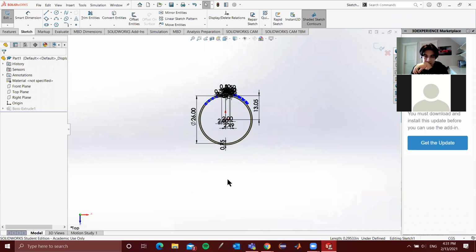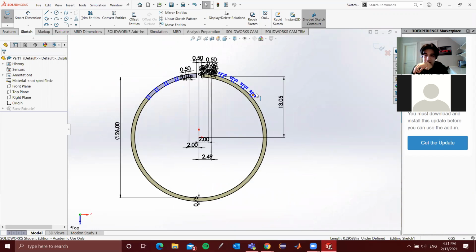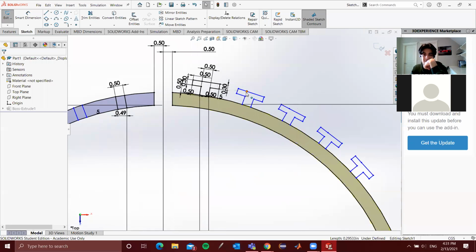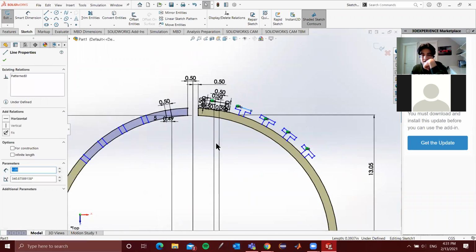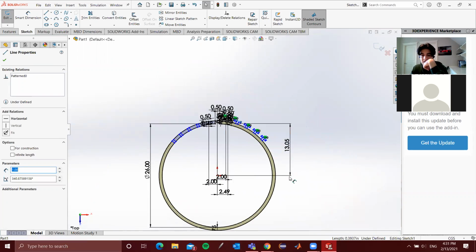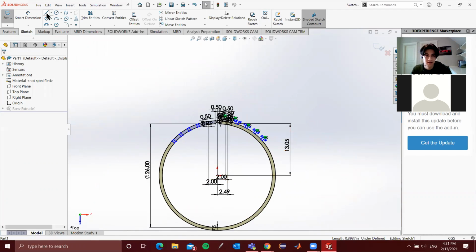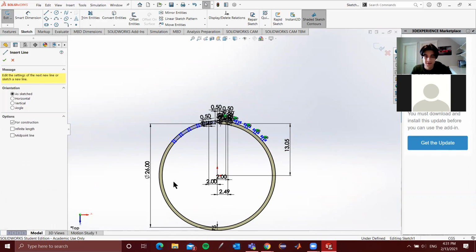So essentially, what we can do is we can reuse these little clips that we had up here, right? And to do that, what I'm going to do is I'm just going to mirror one instance of this one along the x-axis in this case, right? So what I'm going to do is I'm just going to draw a center line. So this is a type of reference geometry.